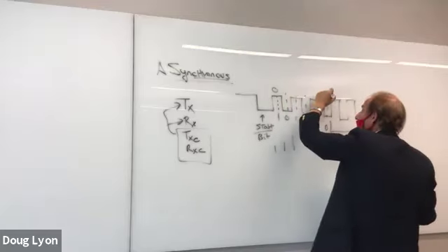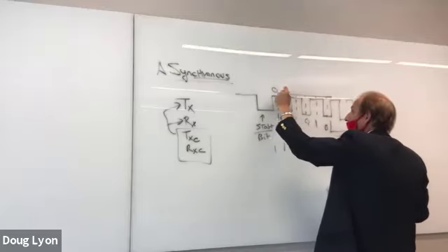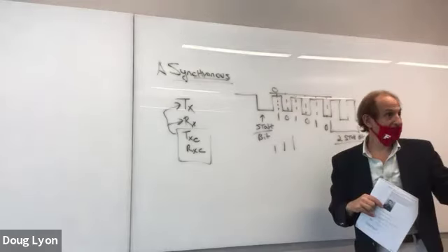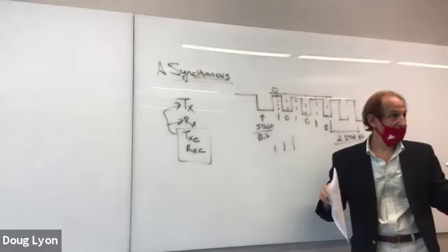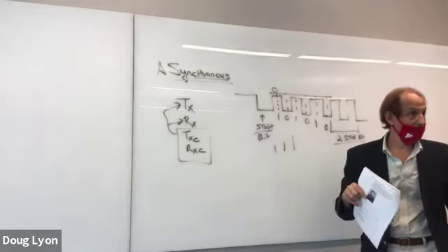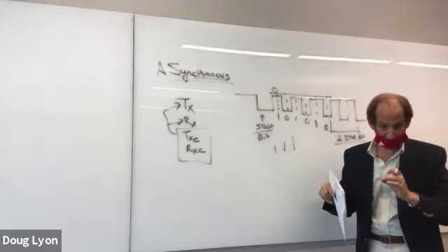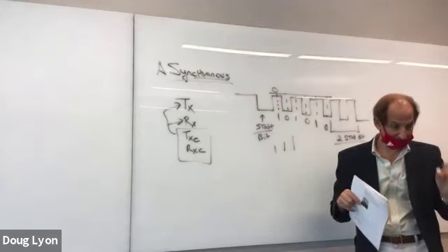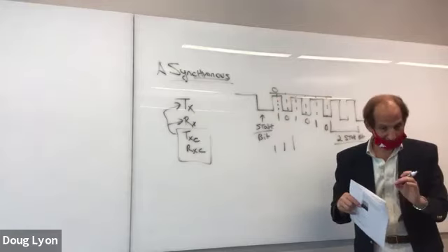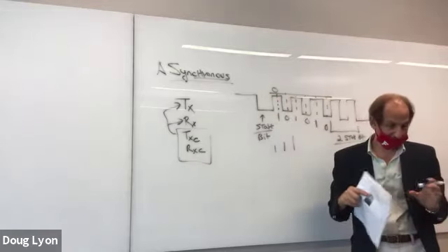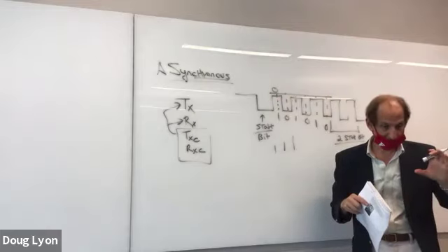And this pulse that comes in is going to shape when your little D flip-flops are going to latch the bit and put it into a shift register. So your goal in taking serial communication bits that are coming in 1 bit at a time is to do a serial to parallel conversion. So you shift them in using your sampling clock and into a shift register and then present them in parallel